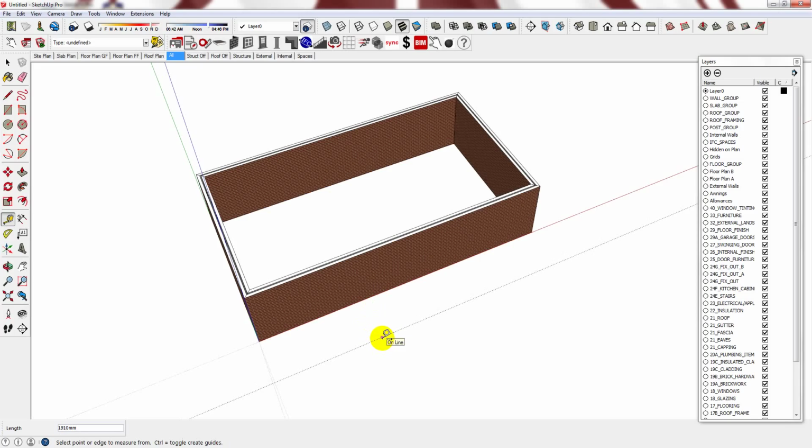Grids are very useful for planning and drafting. However, because it is not part of the Plusspec toolset, it will not automatically be assigned to the correct layer, so you will have to do it manually. Before you draw grids, ensure that you have activated the grid layer.